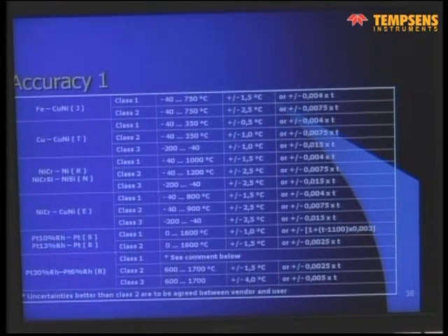Newly in the standards it is mentioned that for cryogenic applications, class 3 material does not necessarily comply above 0 degrees to class 1 or class 2. And vice versa, class 1 or class 2 material must not comply with class 3 at low cryogenic temperatures.